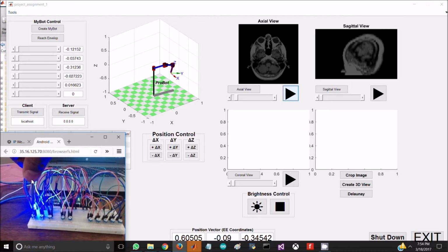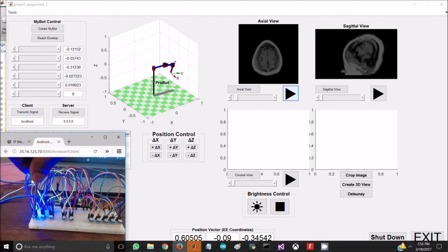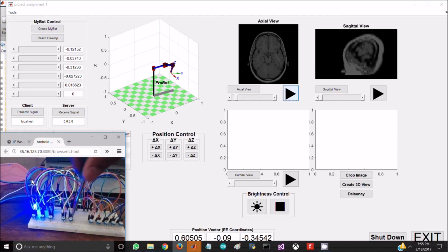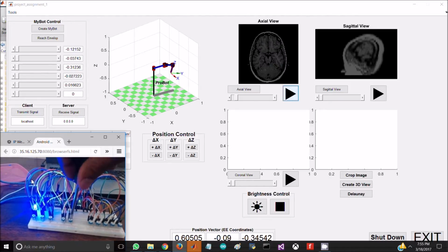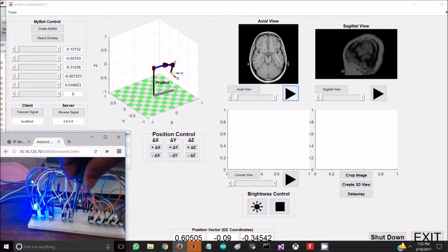While scrolling through axial slices, I can adjust the range using two potentiometers. The axial slice potentiometer is calibrated through 0 to 27. The range selection potentiometers are calibrated through 0 to 255, which is the pixel value of the MRI image.